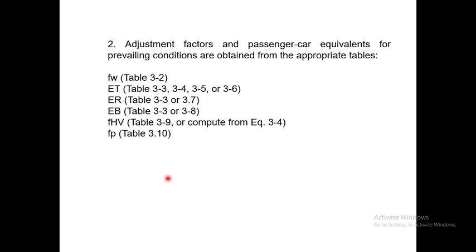The second step is, as I explained for you, you have to calculate all the factors. What were the factors? We had three factors: factor for lane width, factor for heavy vehicle, and factor for population. As I just mentioned, factor for lane is very easy. You can use one table to find it. Factor for population is also very easy.